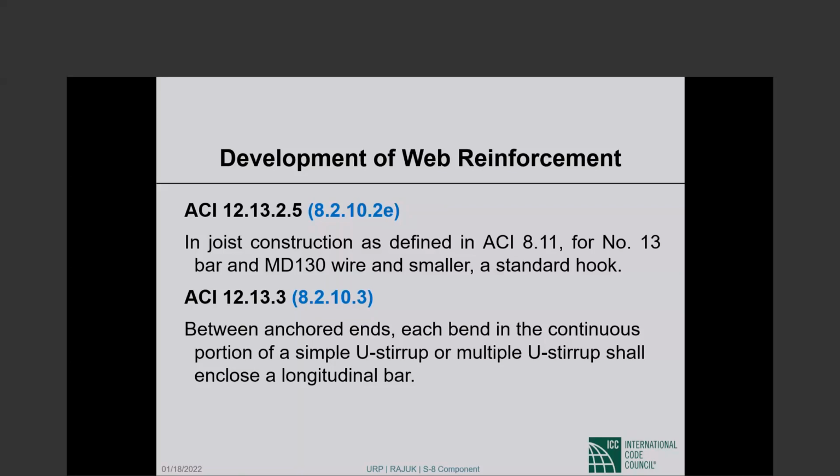The two ends of the U hook around longitudinal bars, but then this U, okay, so you start with, let us say, the left bar at the top. The stirrup hooks around that, comes down, then it goes around a bottom bar, and then it goes again around another bottom bar, and then goes up, and then hooks around the top right bar.